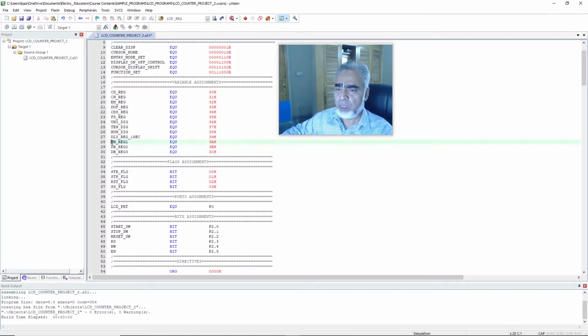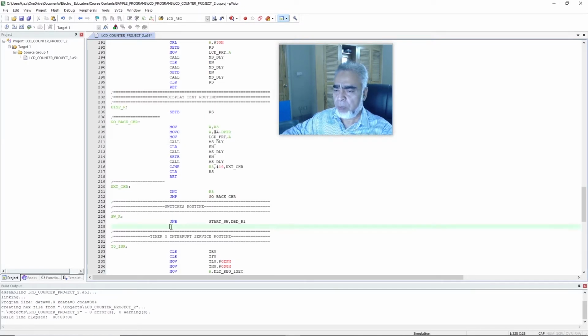So we'll copy this variable from here, Control C, and here we will write that is move debouncing delay register 1 comma hash 00h, and after executing this instruction our program will get returned from this subroutine.